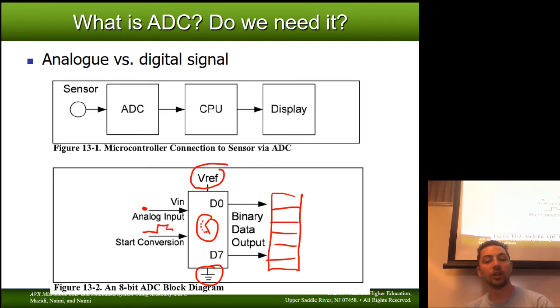So here, the low voltage reference is 0 volts, and here it's Vref. When you get a digital signal that is all ones, that is Vref. When you get 0, 0, 0, 0, 0, 0, that's your low signal. So this basic block diagram has all the pieces we need to talk about any ADC. Voltage reference, analog input, digital output.